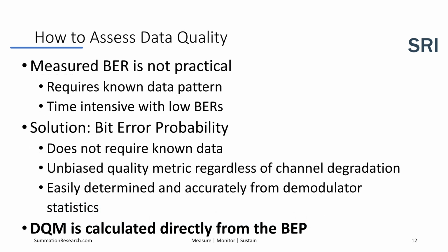How to assess data quality. Assessing data quality in telemetry systems is critical for flight test ranges. We will explore why measuring the bit error rate, BER, is often impractical, and how the bit error probability, BP, offers a more effective solution.